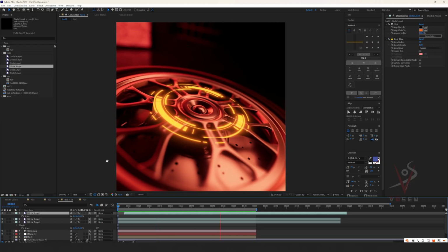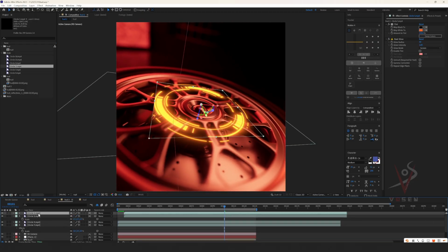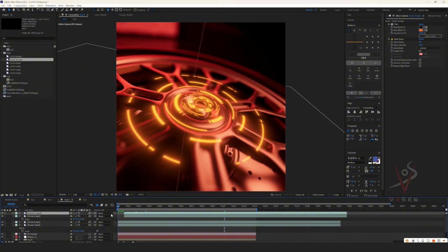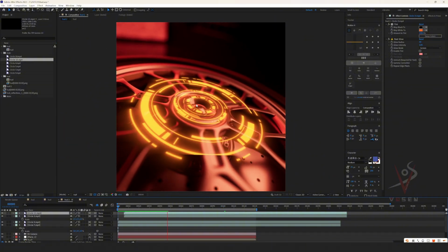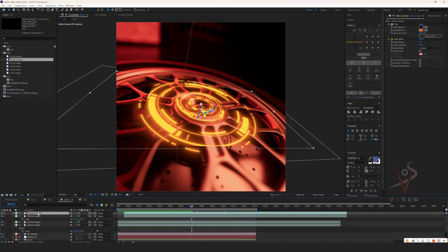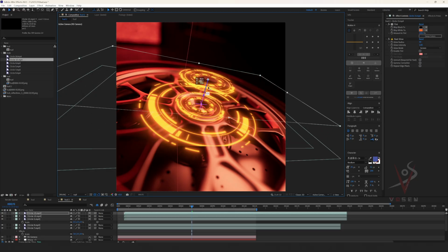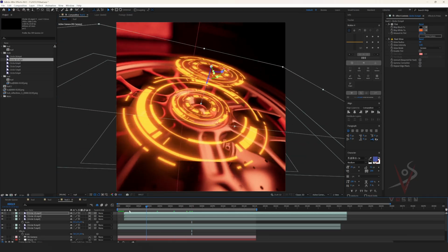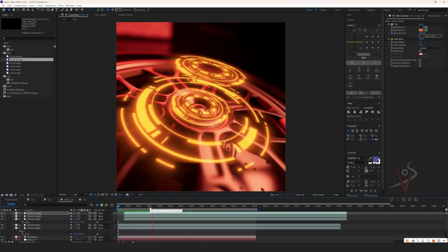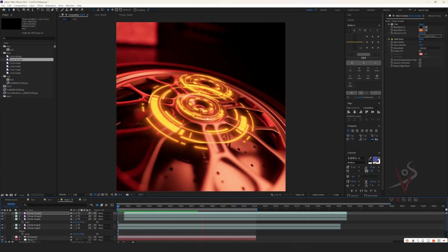One is to composite the HUD. Hold down Ctrl and D to duplicate a layer. And add some others, such as this one, and put it in the middle. OK, press Ctrl and D to duplicate it. Then, raise its Z-axis to create a sense of space.